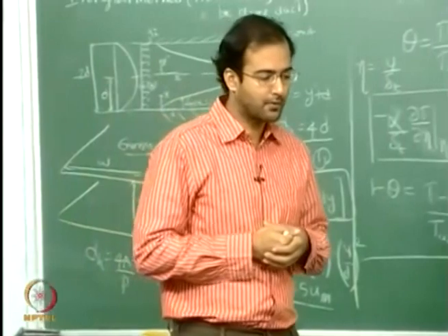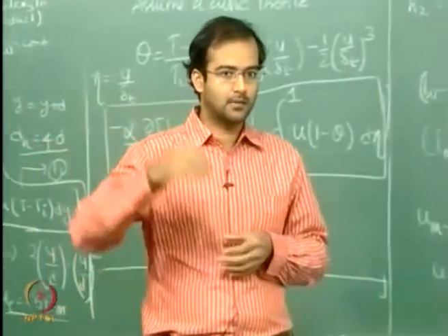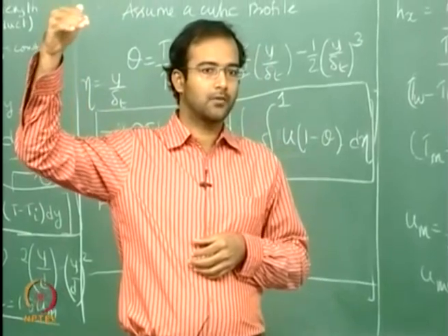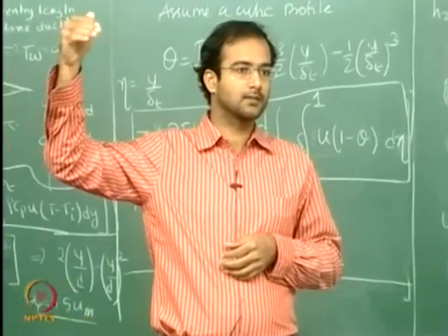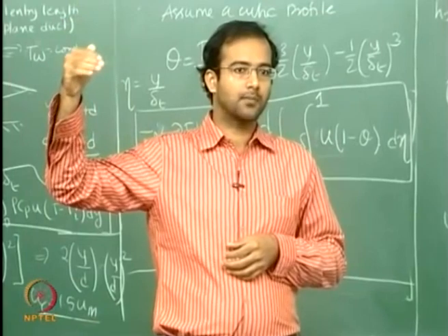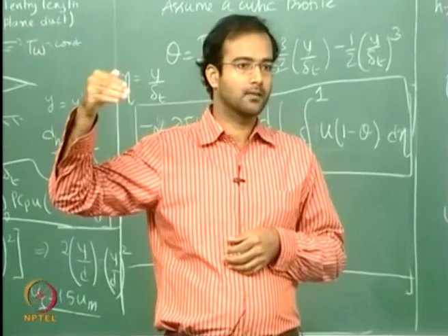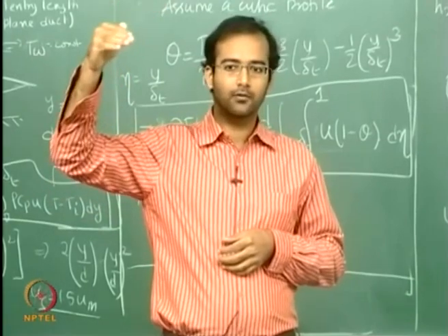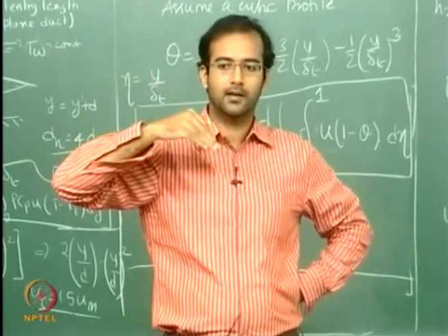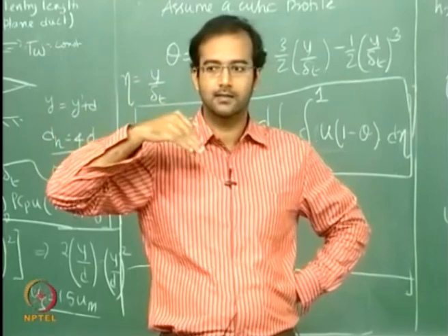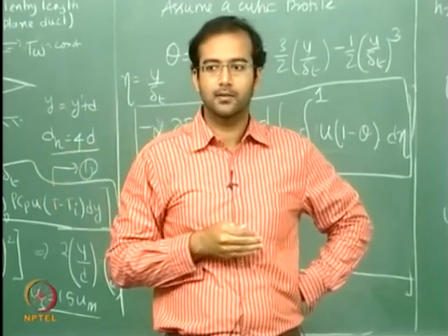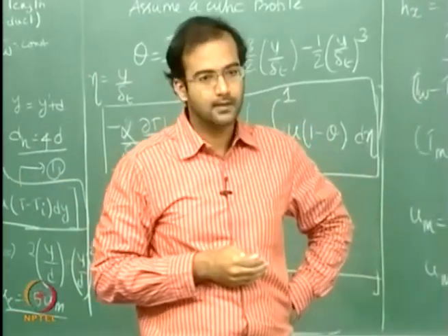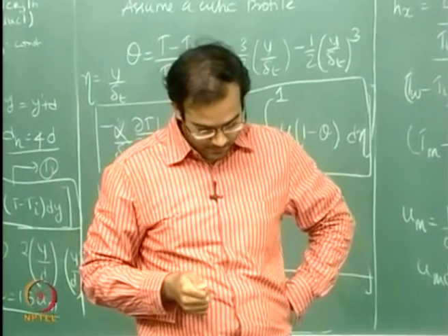And the order of decreasing Nusselt number starts from your channel flow. The highest value comes for the plug flow case with the constant wall flux, then constant wall temperature, then your parabolic velocity flow. So it goes in that order, starting from 2D duct flow, then 3D circular ducts, and finally your triangular cross section. So this is the hierarchy in which the Nusselt number decreases.